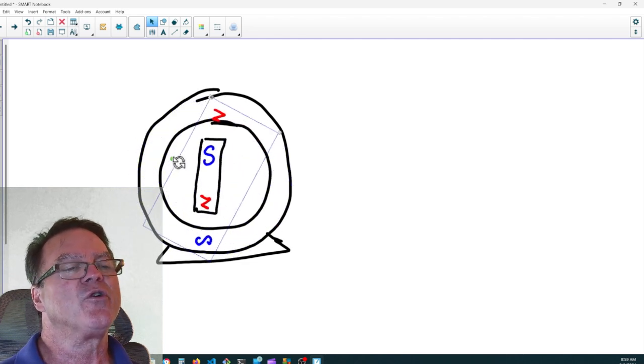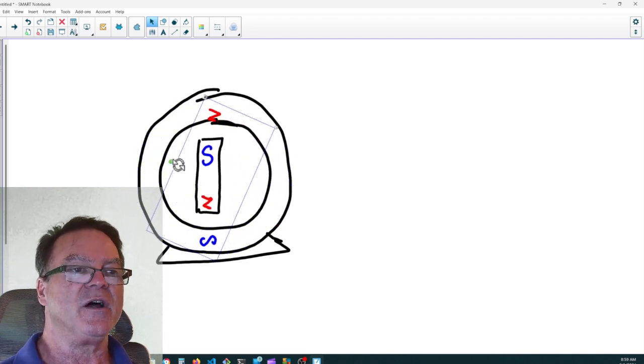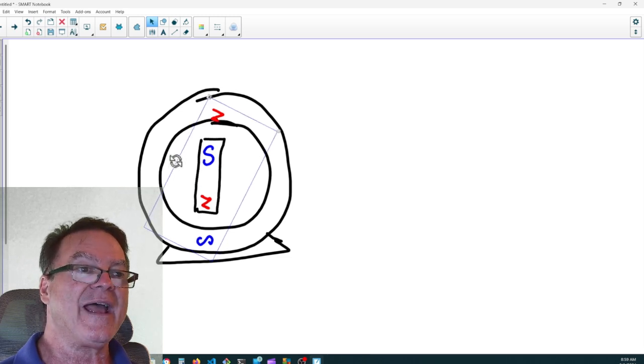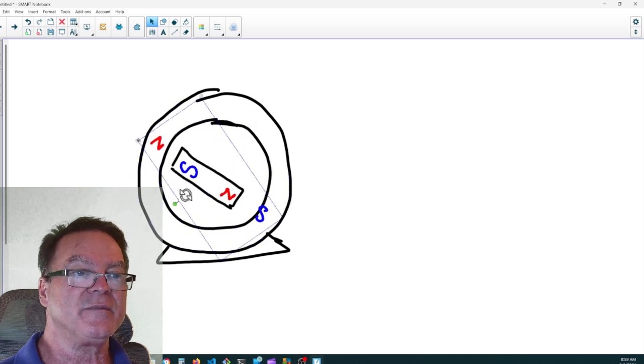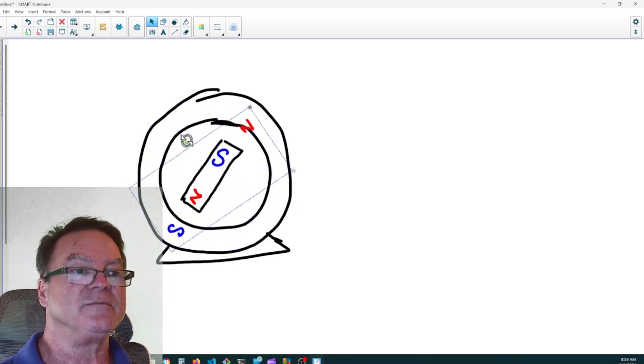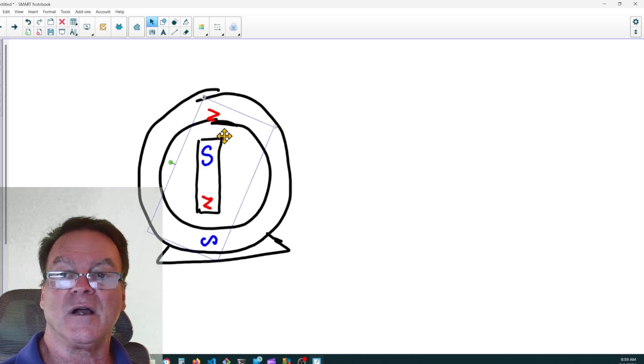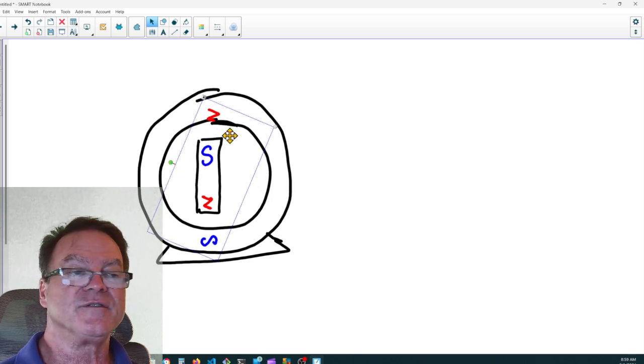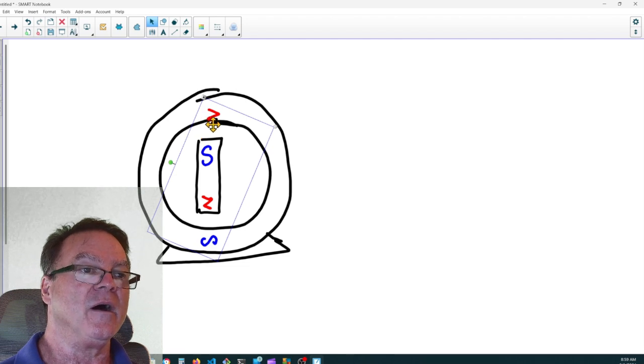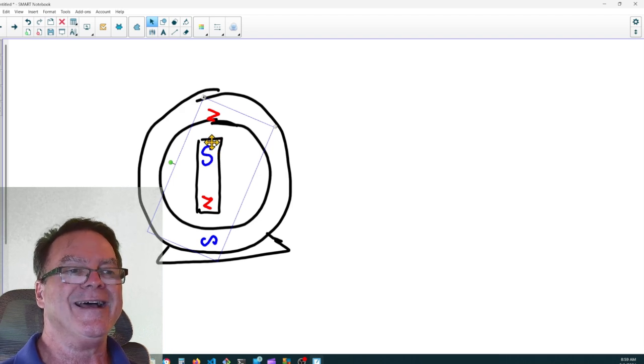beautiful. If you have a rotor that has to induce voltage and current in the rotor, and the south pole catches the north pole and stays with it, guess what? We're no longer cutting lines of flux. The lines of flux are running parallel, or they're running with this rotating rotor.